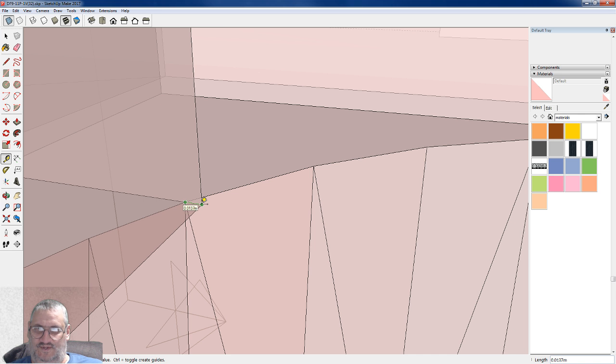How big is that? That line is 0.0132 millimeters. Very small distance. And if we were to actually draw the lines where it had it and make a part based on that, the part would probably be fine. It's probably within manufacturing specs.